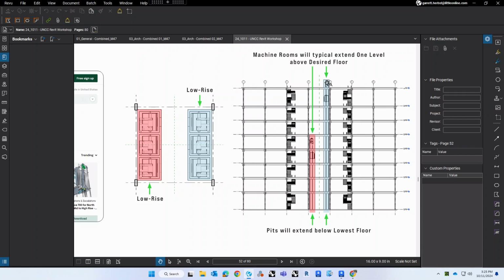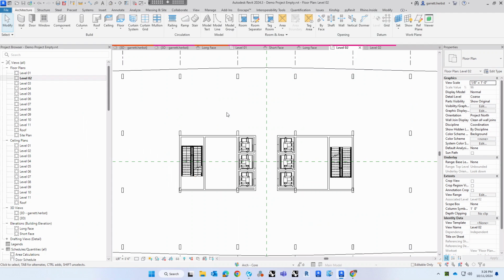All right. And then, of course, I don't know why that did not copy, but you also need to have all of your fun mechanical, electrical, and basically all your infrastructure, as well as the restrooms. So typically restrooms will be in your core. You can put your bathrooms wherever you want in your building, but in reality, you're going to stack them all so that all of your plumbing is above each other. It just reduces cost. So I just made quick boxes. I'll get into that a little bit once I start to put together the occupancy.